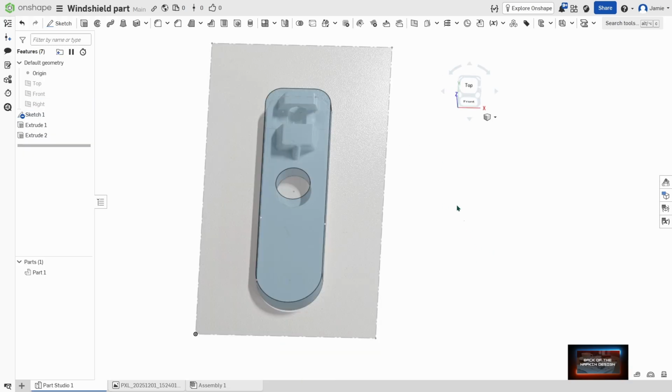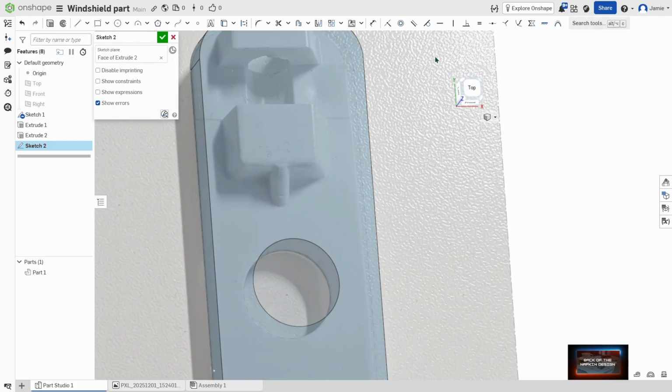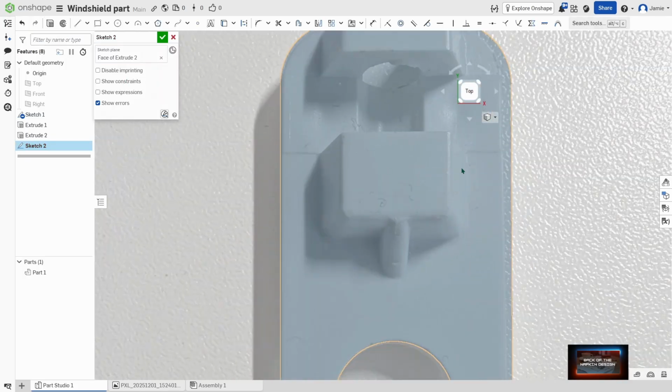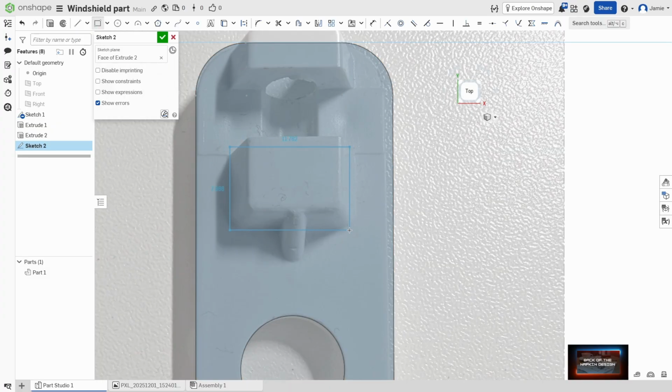All right, so now that we get that first shape done, let's create a sketch on this top surface now. So we're gonna click there, we're gonna flatten this, hit top, and now we can start sketching this out. So I'm just going to go with this shape right here, and then this shape right here. We'll extrude those and we'll put some draft on it. Okay, so let's do that. Let's go click on there, and since I am slightly skewed, I'll keep it like that. So here to here, and I'm going to go up to that. We can go past it if we want.